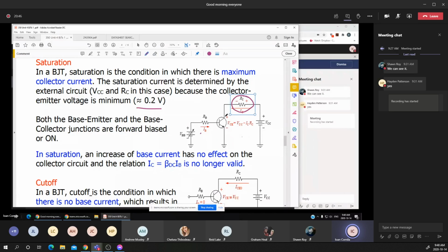voltage. We are making the assumption again that voltage VCE on the saturation is very small, or actually is equal to 0 in our calculation, even if we know that this collector emitter voltage is very small, like 0.2, 0.1 volts. In electronics, if a quantity is at least 10 times smaller than the other quantity, it may be neglected. Remember that we are doing the same approximation when you are calculating the emitter current and the collector current.